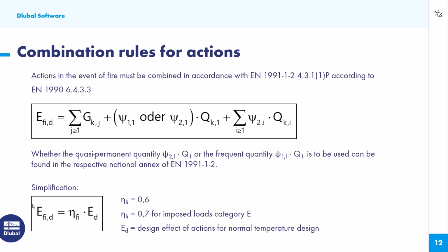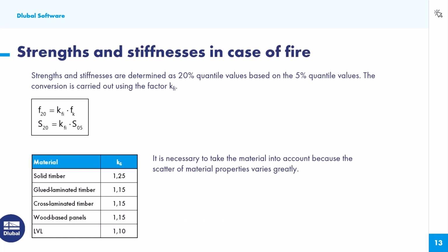Okay, so there's also this simplification where you use the internal forces or the actions from the normal temperature design multiplied by some factor, and you can design with these internal forces, but I do not recommend using this simplification since it is mostly far too uneconomic. All right.